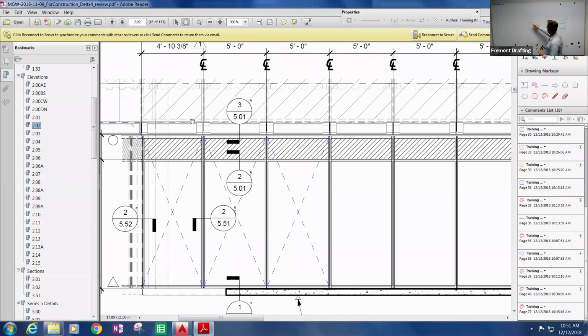So now when this one racks, and it's still racking even though it's a stick wall, it's moved this way, but my horizontals have stayed level wherever it's at. So in the stick wall, the mullion's racked, the horizontals stay horizontal. Because if this one's going over 3 inches, this one's going over 3 inches. So it's probably come down a 32nd or a 16th, but the actual dimension between the verticals has stayed the same.